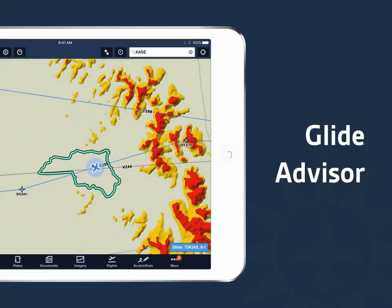Glide Advisor is one of my favorite features. This is a real-time available gliding distance. So if I had an engine failure right at this point, at my current GPS altitude, this is the available distance I have to glide to the ground. It takes into account the winds aloft forecast, and it takes into account the terrain and obstacles that are around you. It only requires two pieces of information for you to enter for it to work: your glide ratio and your best glide speed. That's it.